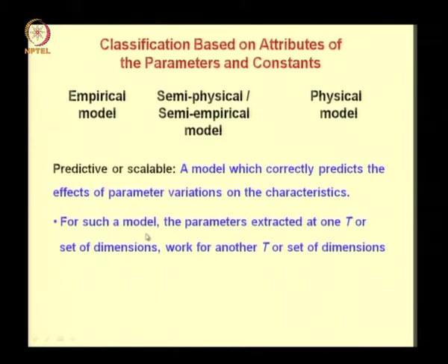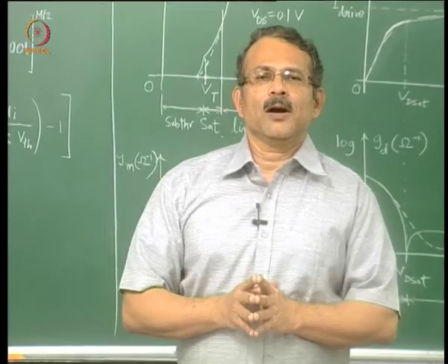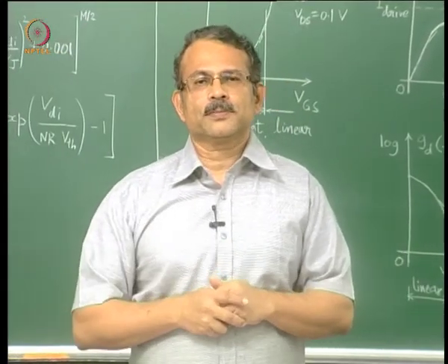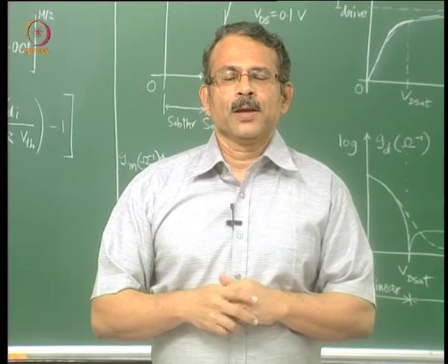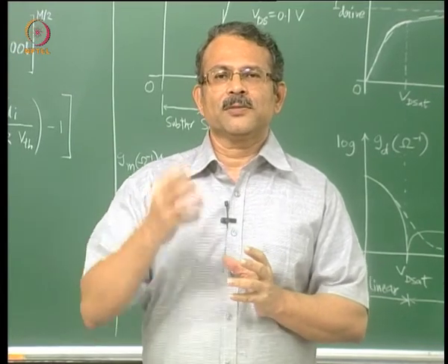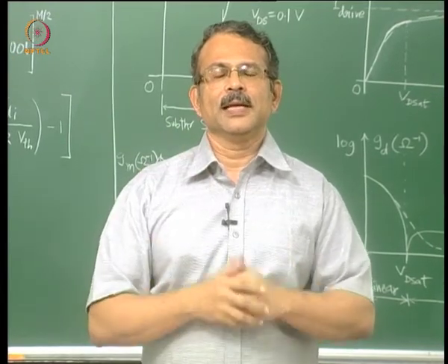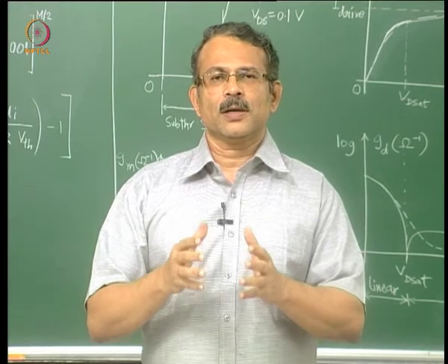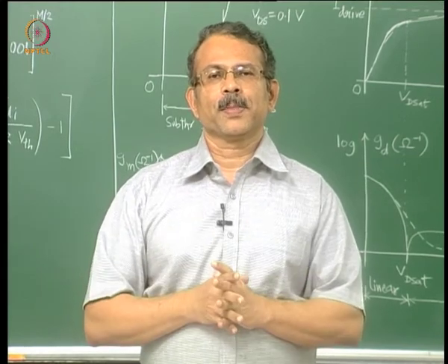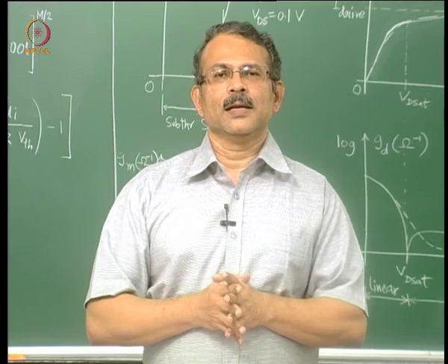For such a model, the parameters extracted at one temperature or one set of dimensions work for another temperature or another set of dimensions. Consider the example of a diode model. If the diode model is in terms of series resistance Rs, we have seen an equation for a real diode in earlier modules.